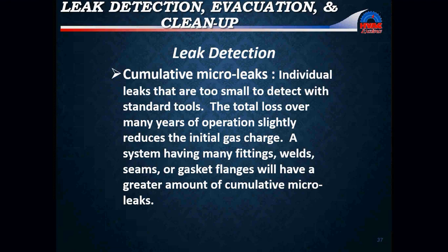Successful leak detection is really solely dependent on the careful observation of the mechanic. We're the ones that are out there doing these things. We're the ones that have to make sure that we're checking for these leaks and doing them properly. All refrigerant systems circulate compressor oil with the refrigerant. Oil will blow off with the refrigerant gas, and oil marks the general area of leaks.